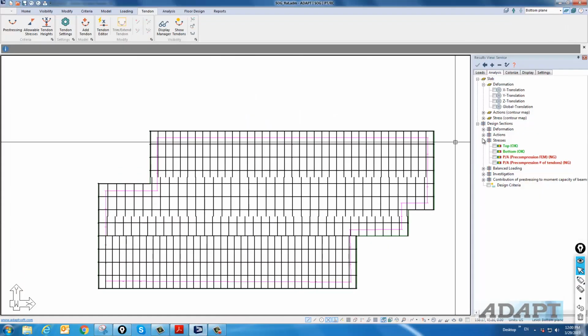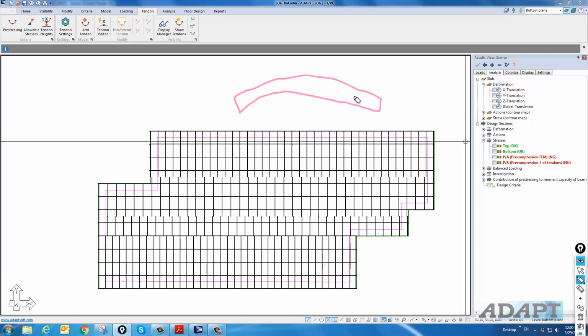So the flexural stress, if we look at the way that this behaves under center lift, if there's an increase in volume of the soil on the perimeter of the slab, then the slab is going to basically do something like this, which means that the top fiber would be in tension, the bottom fiber is in compression, and so we're expecting at the top to have tensile stress and at the bottom to have compressive stress, unless we have so much post-tensioning in the slab that that's overcome and you get a reversal.